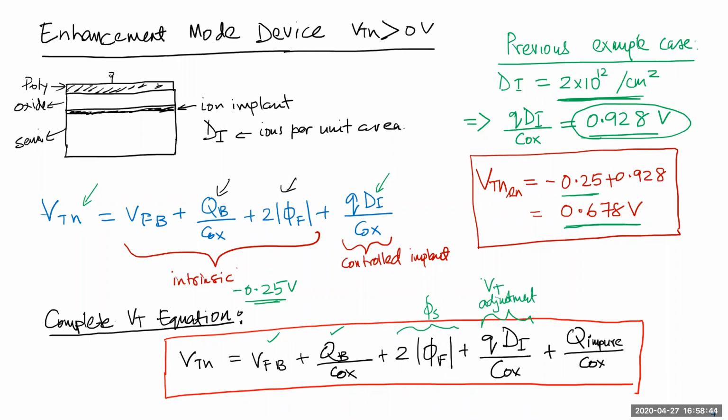And like someone was mentioning last time, when you do standard cells, you'll find different values of VT for different standard cells. And what they have is the layout I was showing, that diffusion area. On top of that, you have another thing called implant. And you choose a different implant.